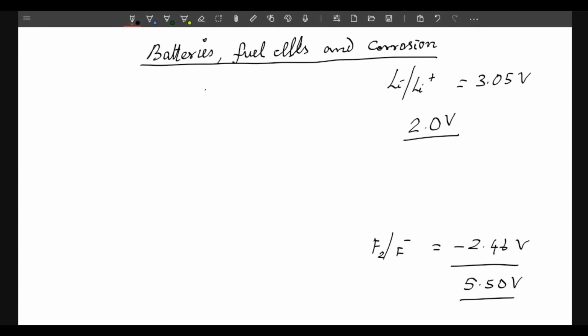Therefore, in such cases, you have to assemble 6 voltaic cells in series. They will give us 12 volt. If you want a 4 volt battery, then 2 voltaic cells will be present in that one, and so on. Depending upon the nature of the work for which electricity should be produced, you can make use of either a battery consisting of only one voltaic cell or a number of voltaic cells.